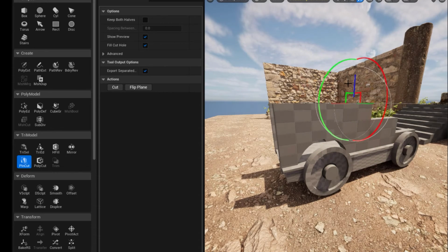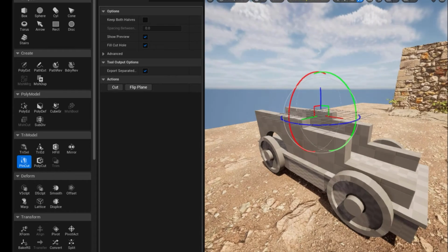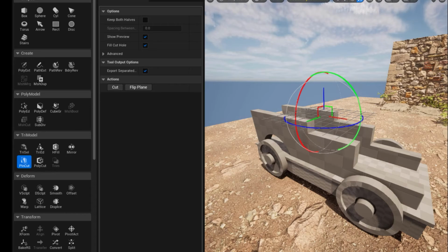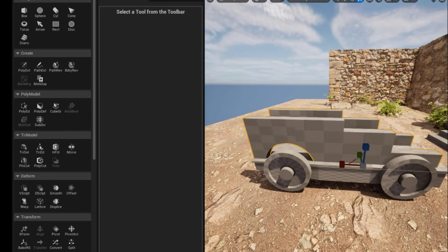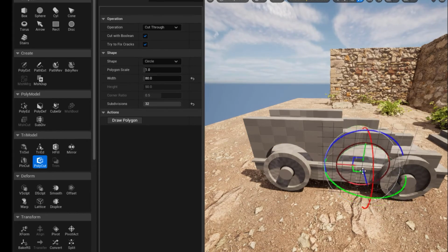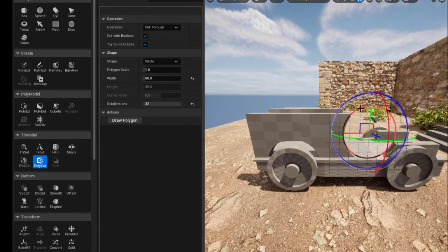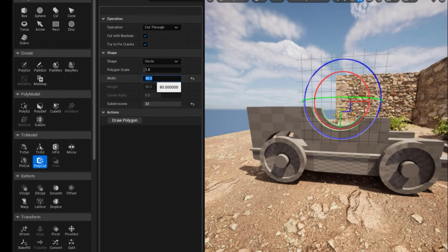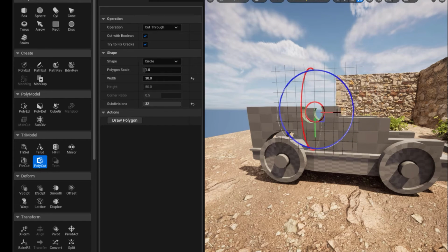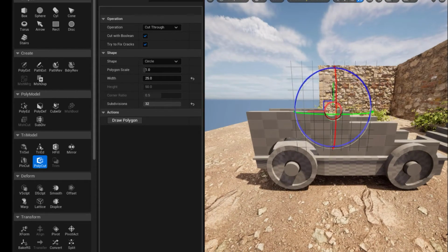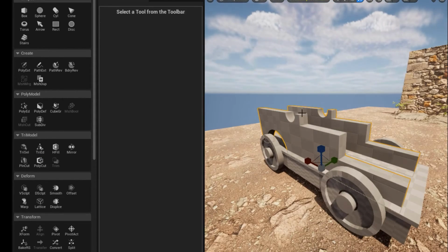You can see how easily you can cut that model. If you realize that what I had was a bit too long, you can just go in there, use the poly cut and have that cut. Again, we did talk about poly cut as well, where you rotate your plane to the side. So this one, definitely the width needs to be reduced to something like 30, and I can just move it here and go accept. So that's where the pole is going to hold the barrel.